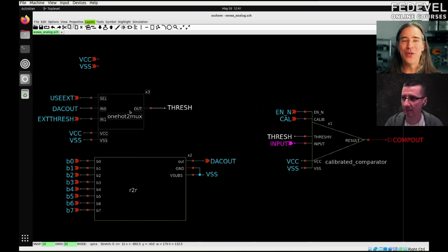And so what I do internally is I say, okay, you're calibrated, set the DAC to 127, high bit high. That's pretty much in the middle. Then I output it through here, it goes to the threshold and compares to the input. Is it higher or lower? If it's higher, I'll keep that bit set. If it's lower, I'll clear that bit. Then I move to the next bit, bit 6. Set that high. Now we're at whichever voltage, that tree we saw.